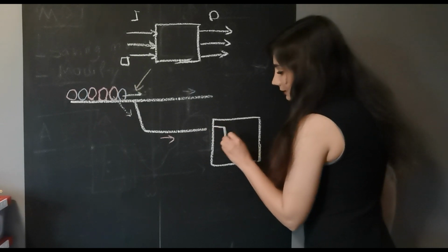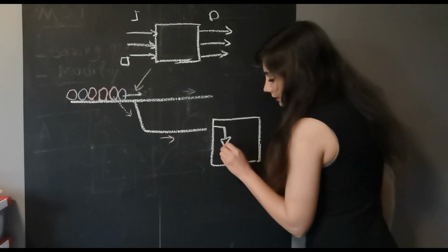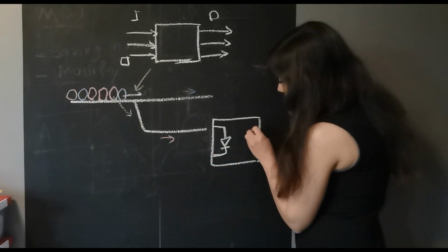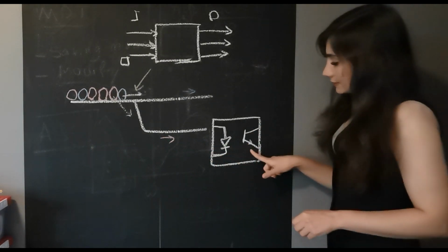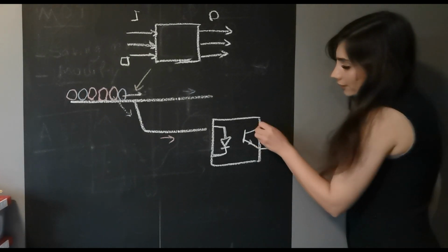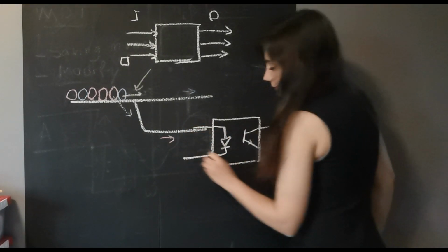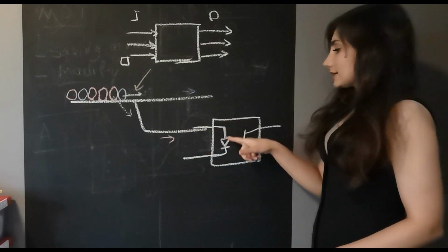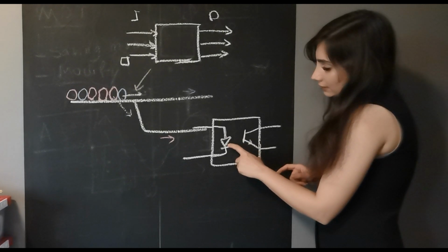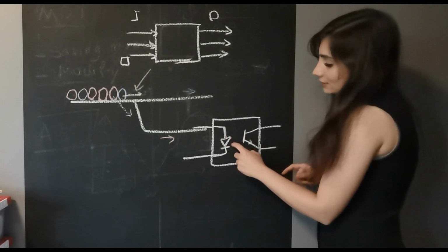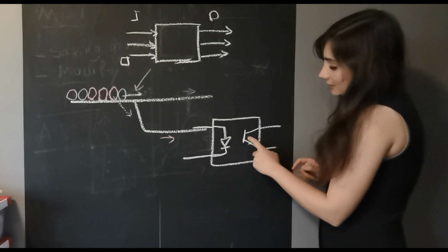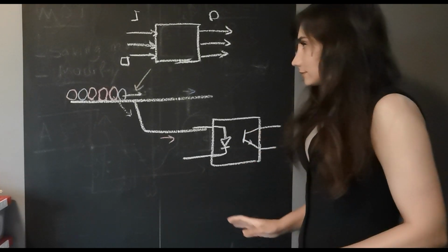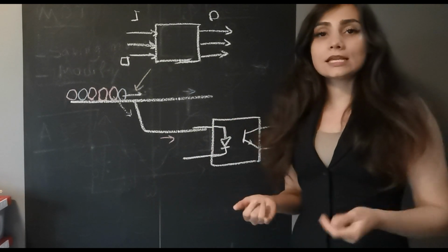It has an LED here. This is coming from the PLC side. And then you have a sensor here. So this is a photo sensor, and this is part of its own circuit, and this is part of its own circuit. The only thing that happens is that the PLC is sending a signal, and the LED lights up. This photo sensor picks it up and turns on the other circuit. So yeah, this is the basic idea behind the PLC.